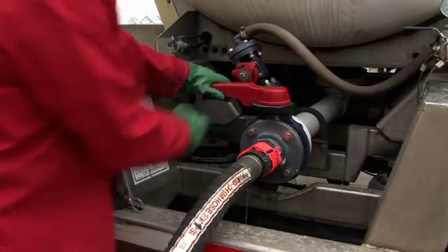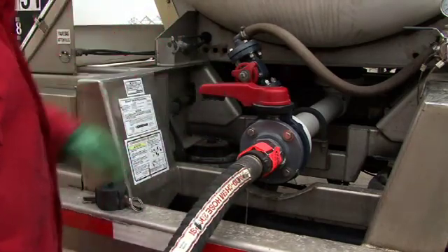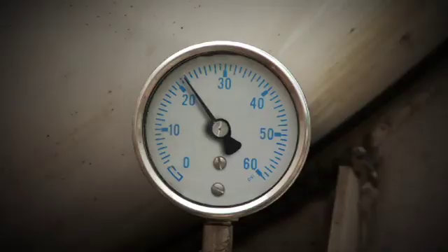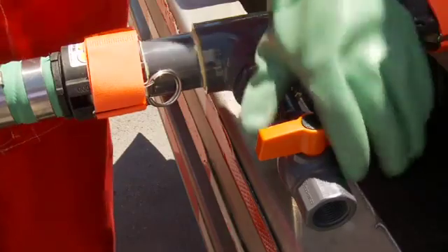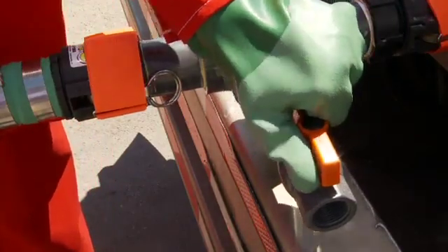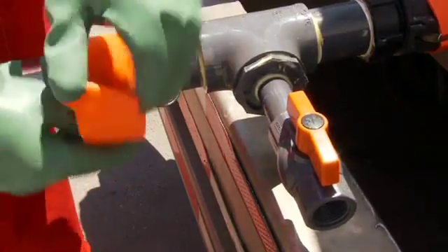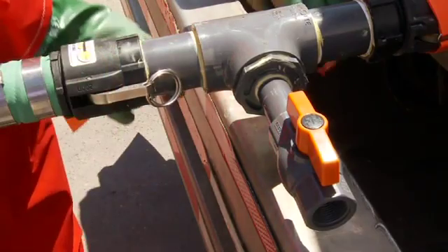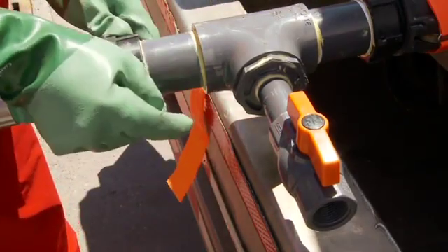Follow your company's procedures for disconnecting the delivery vehicle from the storage tanks. Consider both the potential air pressure and the residual liquid in the unloading lines. Vent and drain as required prior to disconnecting the hose. Disconnecting pressurized lines can be very dangerous to personnel in the area.